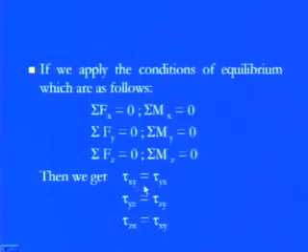So if you are talking about those things, then we can say that tau xy is exactly equal to tau yx, because if you are talking about the frontal part and the rear part, they have symmetricity and there is no change in the force. We can say whatever parallel forces are set up in two different domains as well as two different directions, they are equal, because they are equal and opposite. That's why we can say that the summation of forces are equal. So similarly, if we apply this symmetricity to this object, we can say tau xy equals tau yx, tau yz equals tau zy, and tau zx equals tau xz.